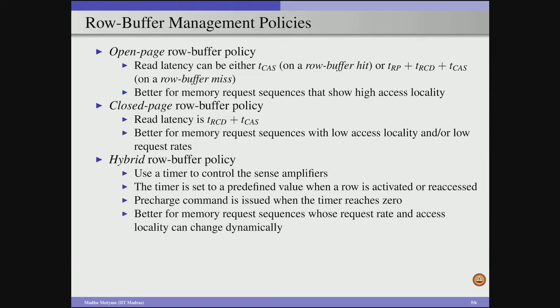And this type of policy is efficient for all those applications which exhibit very low access locality or low request rates. If applications are not generating frequent requests to a DRAM bank, then we can always go for this closed page policy. And an intermediate between the open page and the closed page policy is a hybrid row buffer policy. In this hybrid page policy,